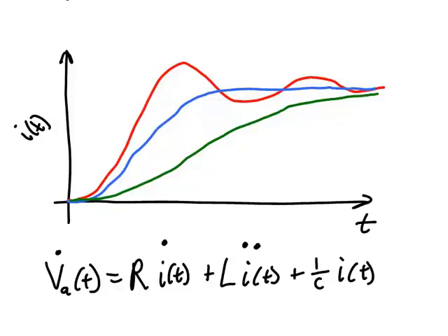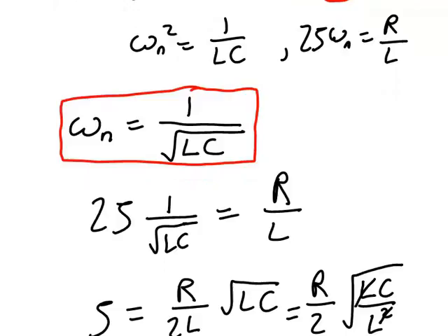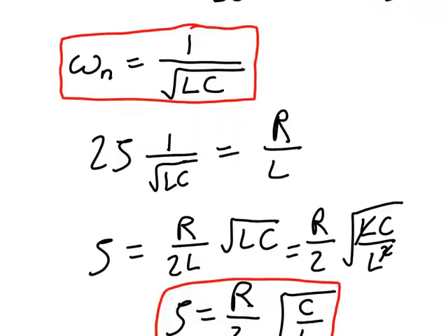You can also set the values of these parameters in order to prevent disasters such as a forced frequency overlapping with the natural frequency.